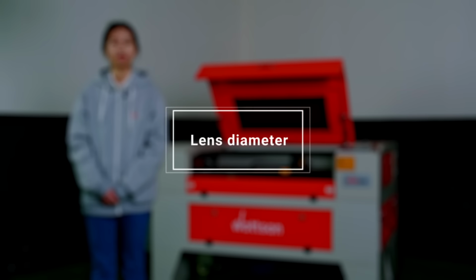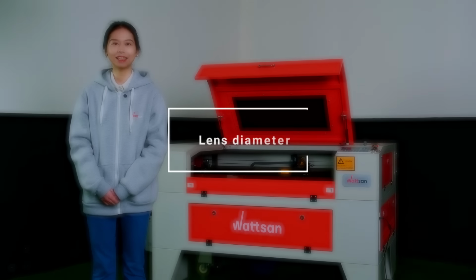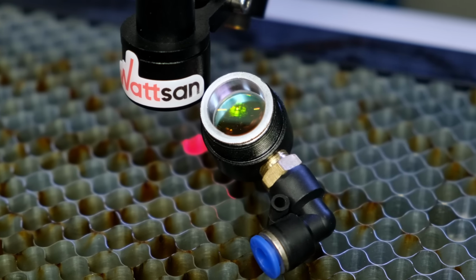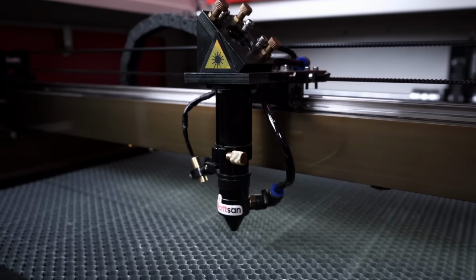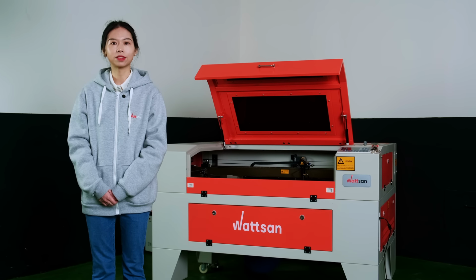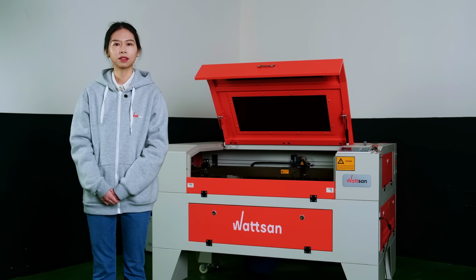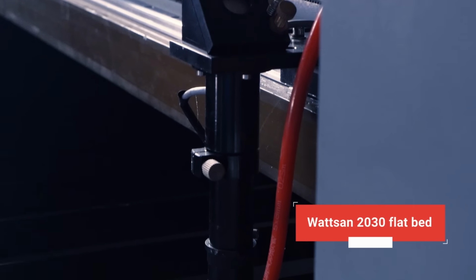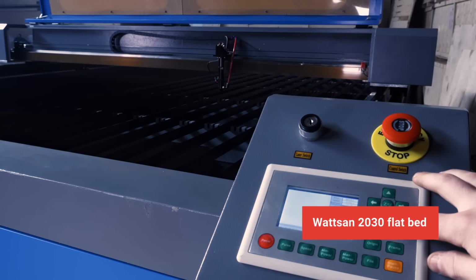Lens diameter. The lens diameter is indicated in the name by the letter D and depends on the type of laser head installed on your laser machine. The most common diameters are 18, 20, and 25 millimeters. Lenses with larger diameters are used in machines with a larger working area for two reasons.